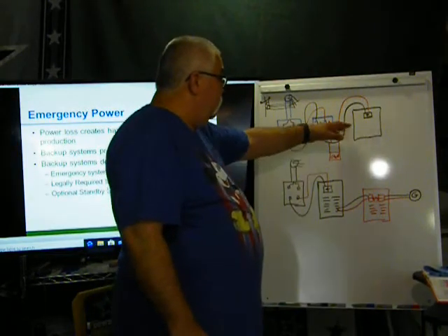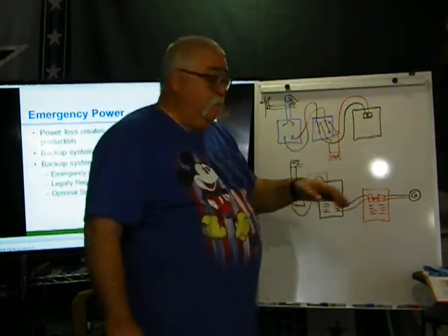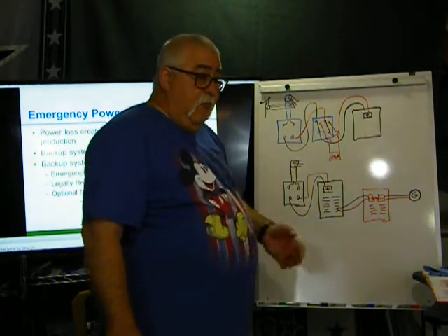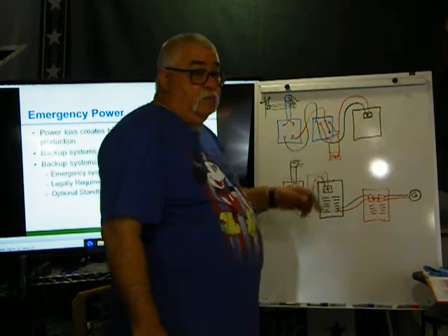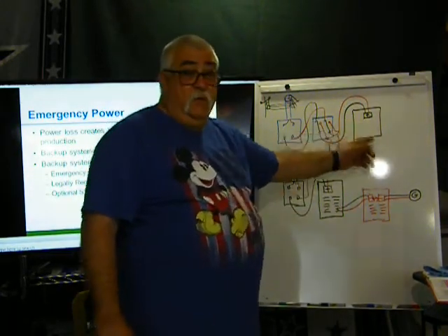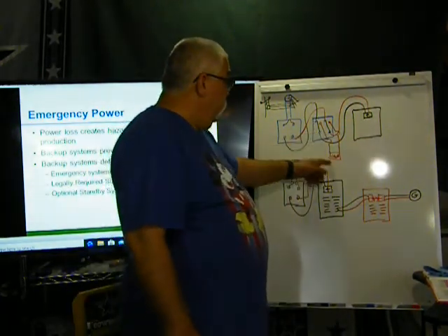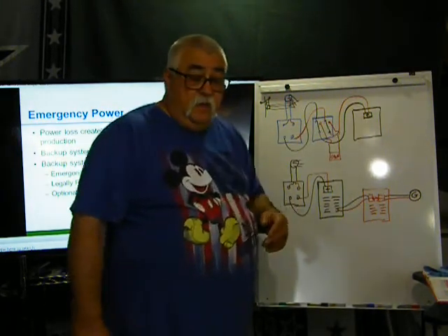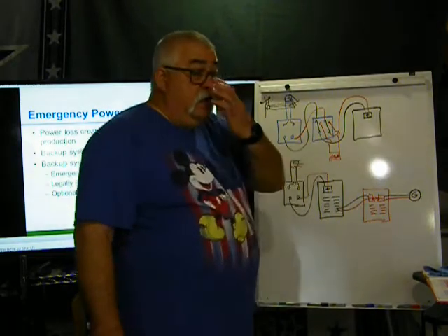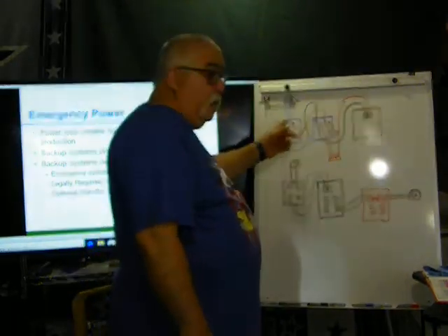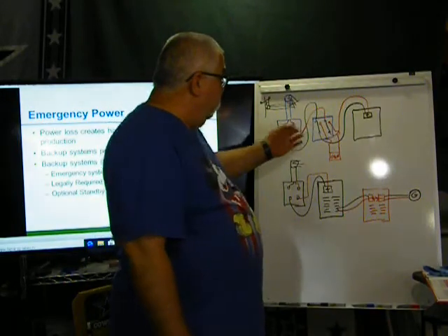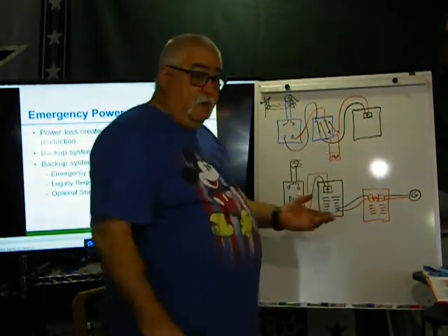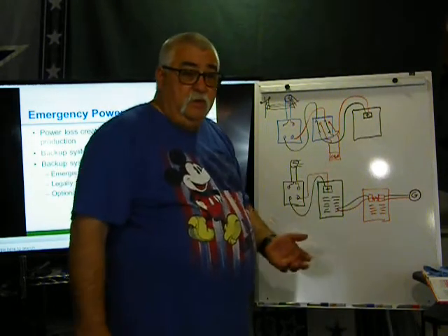Okay, the only thing with this is, if I've got a 400 amp, or say a 200 amp or 400 amp panel, you have to size that accordingly to whatever your load is. So if this generator has to carry full load current of everything applied, then it has to be sized accordingly as you're doing the service. So if I've got a 400 amp service, guess what? My transfer switch is going to have to be a 400 amp transfer switch. If I have a 200 amp service, my transfer switch would have to be a 200 amp.